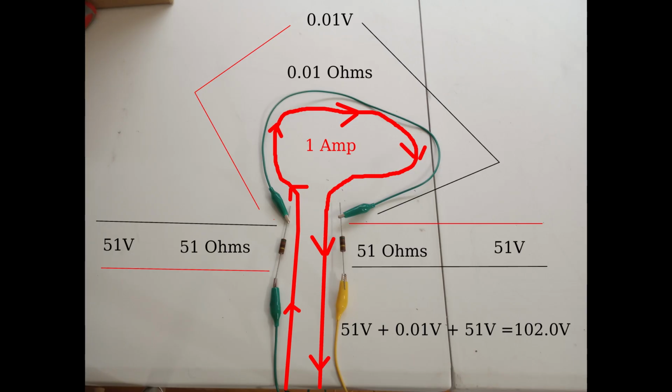From this, we can make two observations. The first is that nobody's going to notice if we just ignore the voltages dropped in the wiring. The second is a little less obvious, but if you notice the way I've been marking off with the red and black lines, you can see that 102.01 volts should really have been written as a negative voltage for the way I've been labeling my voltages. This is like if you go for a walk in your local park and you come back to the same place, you know you must have gone uphill the exact same amount that you went downhill.